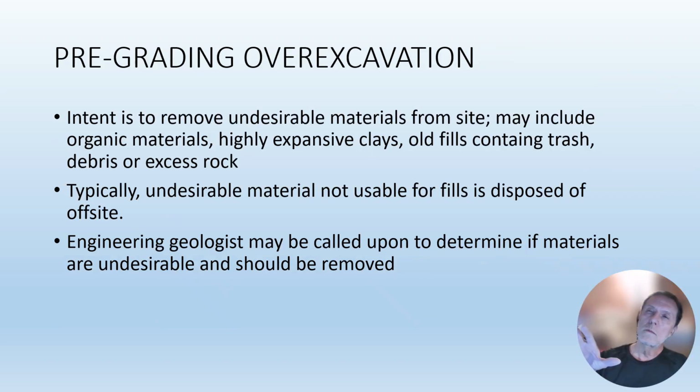So what do you do before you actually start grading according to the grading map, the grading design that is generated by civil engineers and architects? You want to get rid of all undesirable materials. You dispose of those materials off-site. And the engineering geologist may be called to determine which materials are undesirable and should be removed, and which materials maybe you can mix with suitable material. That can happen too.